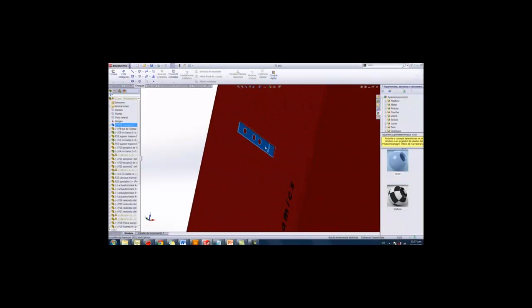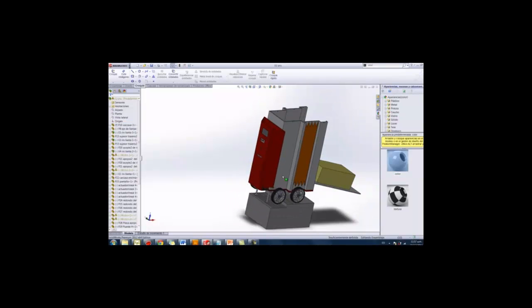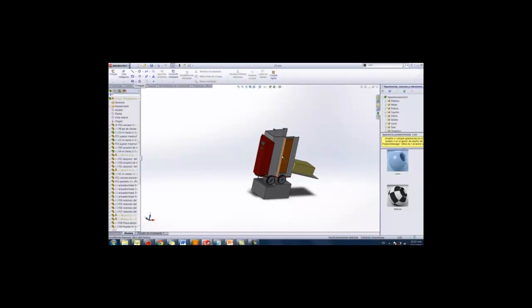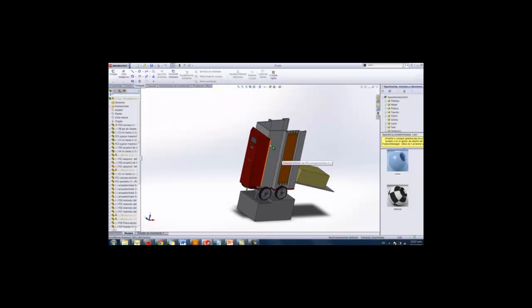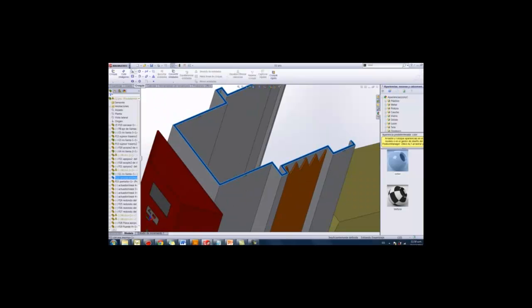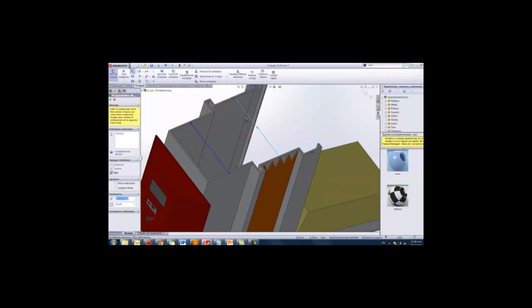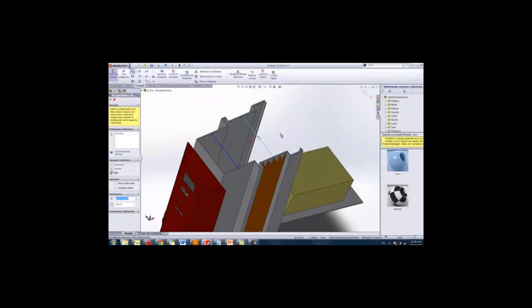Returning to the CAD model, to follow the person's path a Kinect will be used, which faces the person. Security measures will be taken to indicate if the person is lost, there is a sudden change, or more people cross, or in places with little traffic. Another safety measure will be located on the top of the robot, through a system of infrared sensors located in these holes, creating a mesh to detect if someone is stealing some part of the load. In this case, the robot will stop and beep through a buzzer integrated into the front panel.